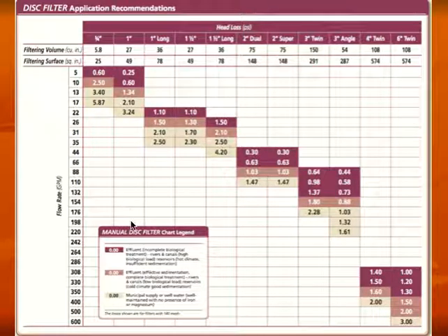Also, looking at the chart here, it gives color codes for different qualities of effluent, showing here at 5 gallons a minute. The purple would be septic tank effluent. The lighter colored would be for a little cleaner effluent, and for potable water, or in our case, when we're treating to, say, treatment level B, where our BOD and TSS are less than 15, lots of times less than 10, we could go to a much higher flow rate through these disc filters. There's just not that much debris there to catch. But in any event, we still want to bump up to the 1-inch, even if we are treating the effluent prior to the drip field.